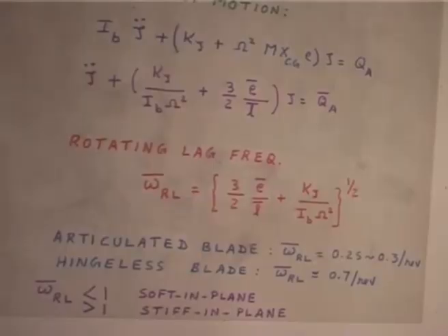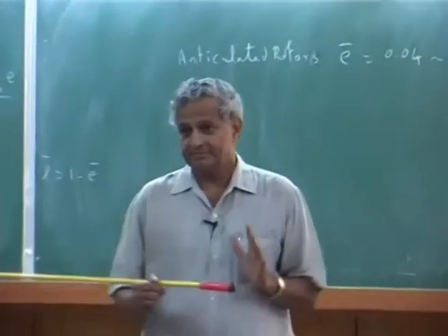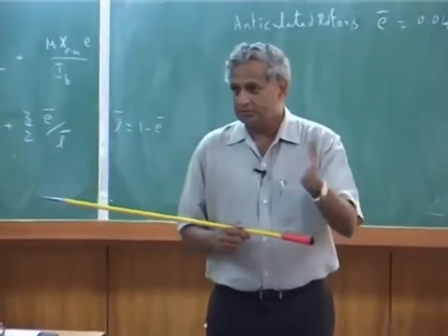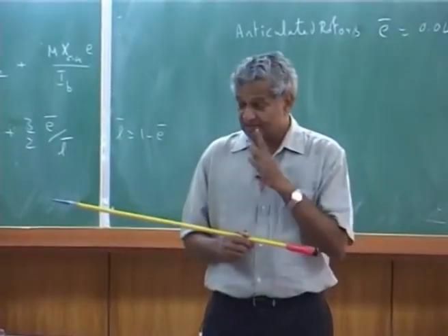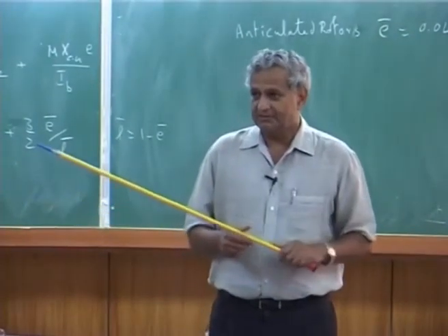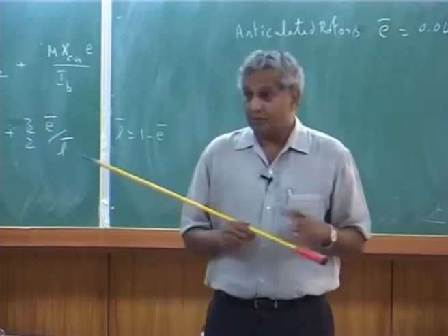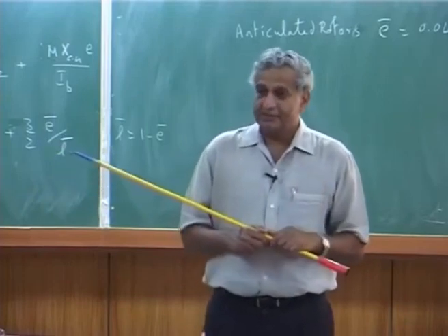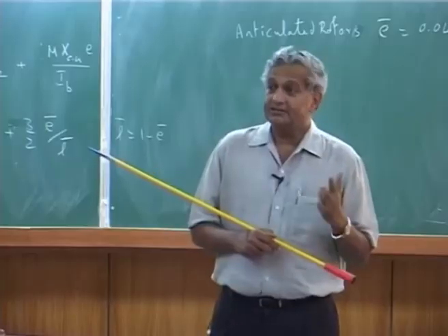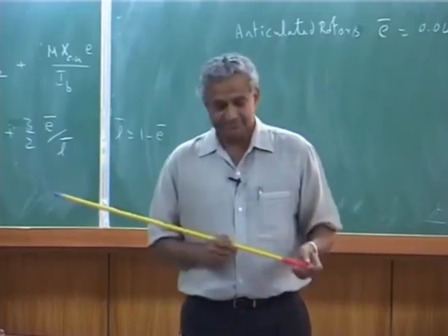I do not know who all came that day for that presentation. That is a ground resonance, in which blade lead lag motion coupled with the body motion, and that will be very catastrophic actually, and you have to avoid that. But the loads are less, vibratory loads.